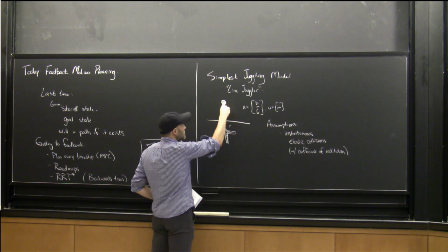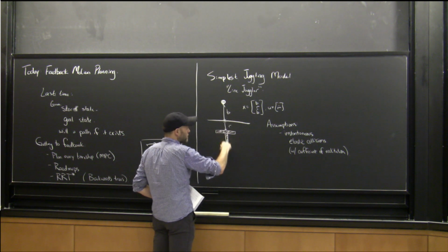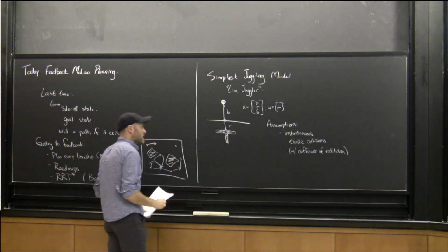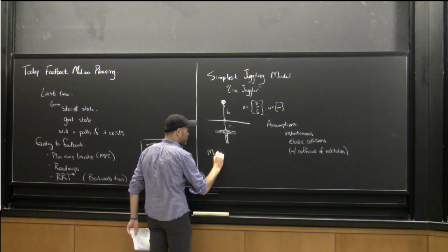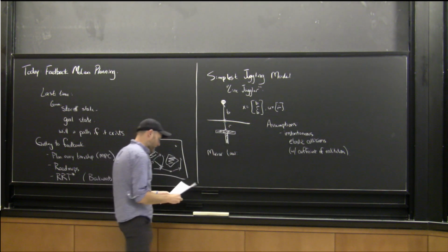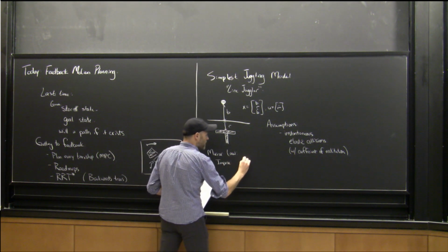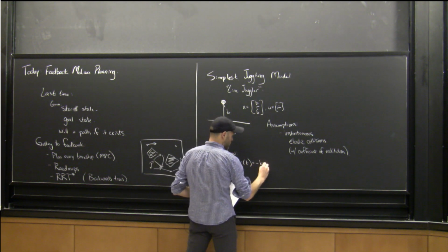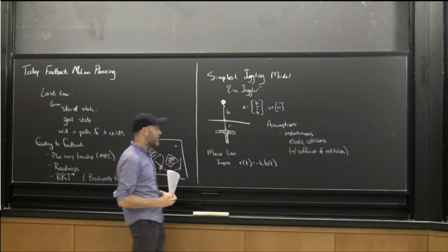So, of course, it's not hard to integrate forward the equations of motion of the ball. But the impact conditions could be arbitrarily complex. And they wrote down this idea called the mirror law, which is that you could impose in your controller that r(t), basically my trajectory, was the mirror image of the ball trajectory multiplied by some gain k.